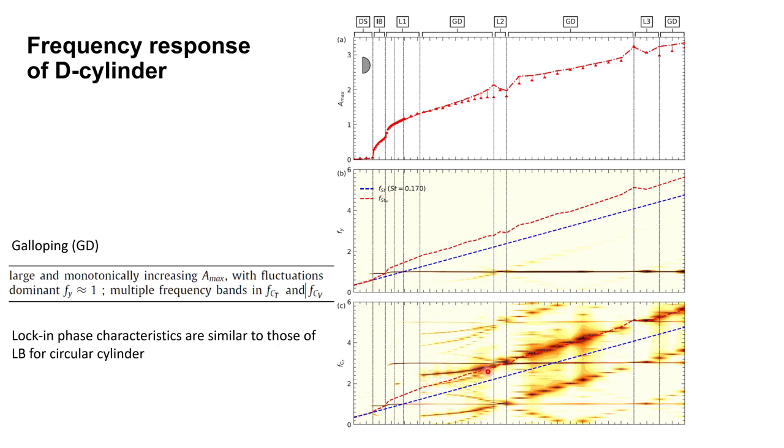It is close to the red curve. And then what really happens is that at some point, all of the frequencies appearing in our forcing signal lock again. They come closer again. As you can see here, this is the third harmonic of the natural frequency. This is the dominant one, the modified natural, and they lock again.